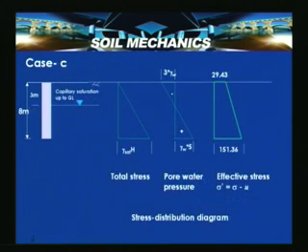Now consider a case where you have a soil which is prone to capillary saturation. Let us assume complete saturation is possible in this particular zone, the entire capillary fringe develops here. So this is a 3 meter zone, and 5 meters is saturated with water, this is the groundwater surface.